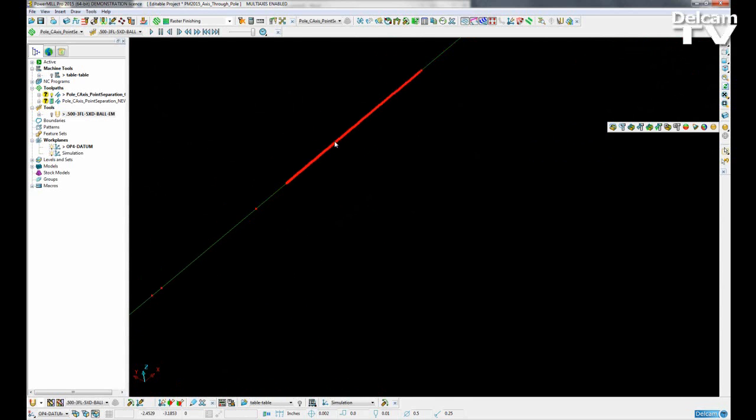So what we need is a method of clearly defining the position of the pole within PowerMILL. Behavior of the toolpath around the pole should be definable to give the best results. What we want to do is maybe avoid the pole or force the tool axis through the pole. If we have a machine tool defined, then that should be used to determine this behavior.